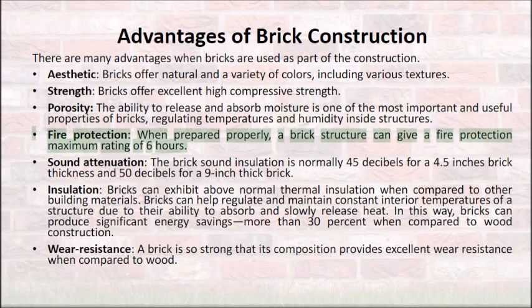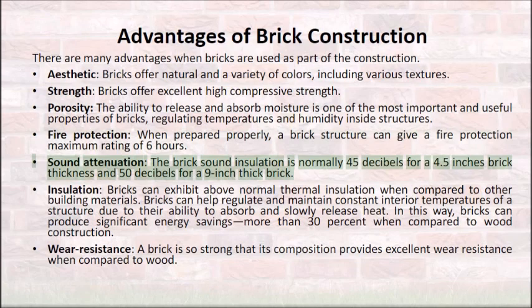Fire protection, when prepared properly, a brick structure can give a fire protection maximum rating of 6 hours. Sound attenuation, the brick sound insulation is normally 45 decibels for a 4.5 inch brick thickness and 50 decibels for a 9-inch thick brick.